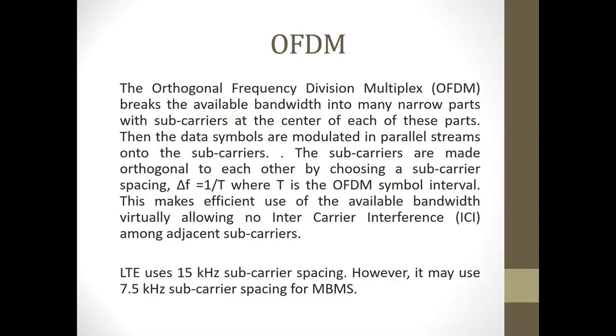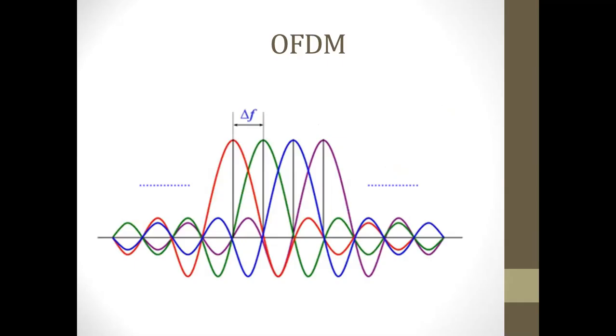So this is why people did not go for splitting data and transmission on multiple subcarriers until OFDM was invented. But OFDM was invented with the solution that there would be orthogonality among the carriers, and so you can use it now without any requirement of margin, or with the use of nominal margin.